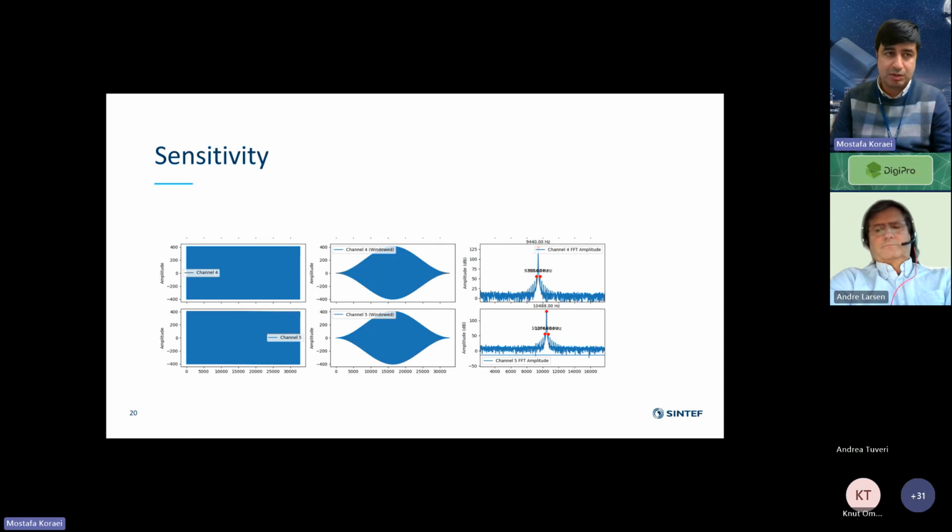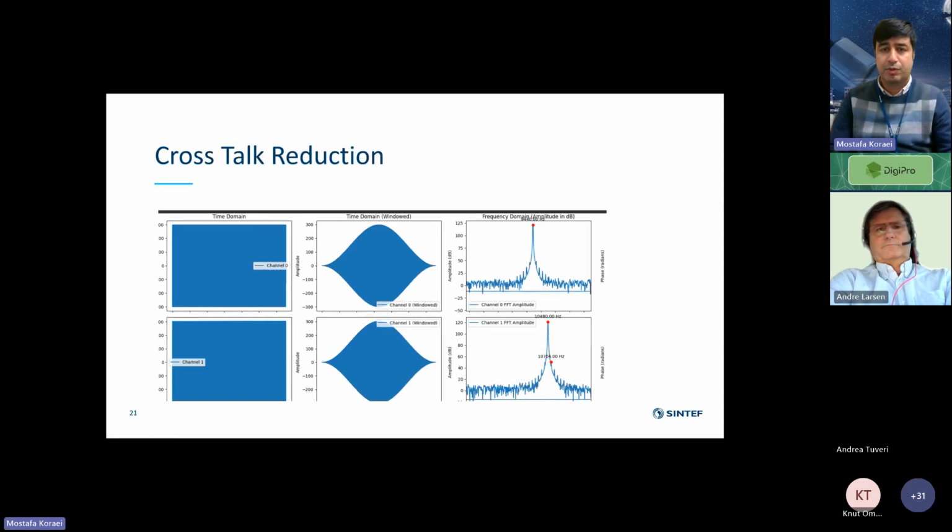And we also checked the sensitivity on even smaller signals while they are close together with a very strong and a very weak signal, to be sure that there is no crosstalk, and it was very good. Actually, we got about 8 dB better signal to noise ratio than the lab systems that we had here from Kista.